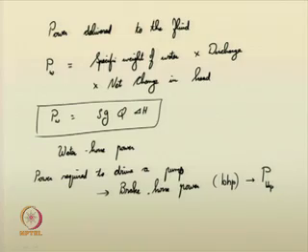This is the amount of power you have to supply to the pump, then only the pump will be able to supply a power Pw to the fluid. What does that mean? Theoretically, the pump requires more power and some of the energy is lost due to various losses, water losses and all. Subsequently, the amount of power transmitted to the fluid is Pw.